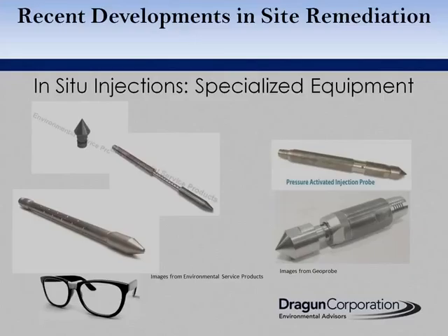These are the two long injection tools on the left side of the slide. We've observed some noticeable improvements in injection coverage when using the sleeve-type tooling. The pressure-activated tool also had some promising results, but was subject to frequent mechanical malfunctions, from soil grit clogging to perforations.